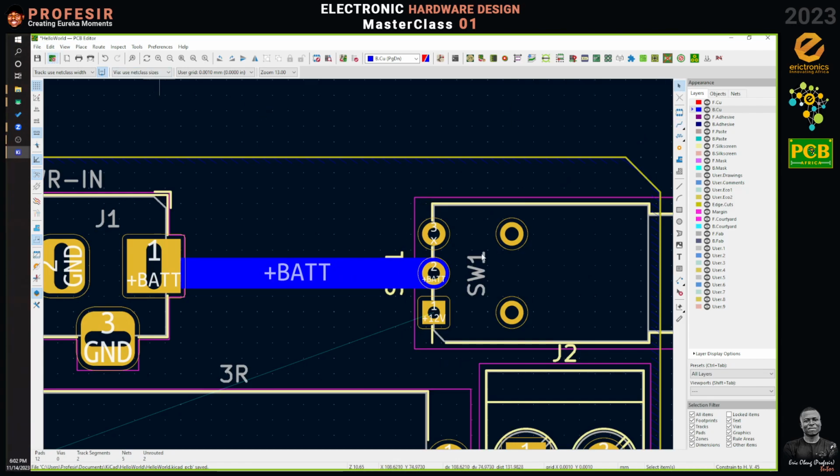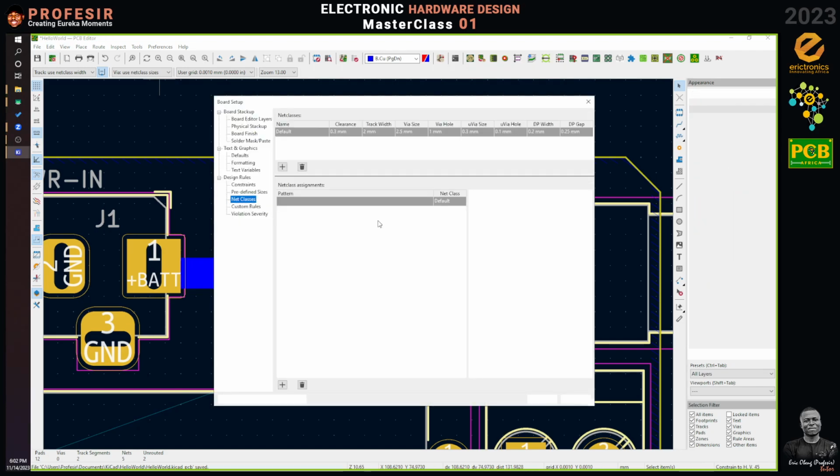After doing this, I can then go back. This is a special case because the pitch between the pins is what is making us do this. This is not an ideal thing to do, but we don't have any choice. So we can now come back here and set our clearance to 1 again. Of course, we are done routing the thing that was a problem.